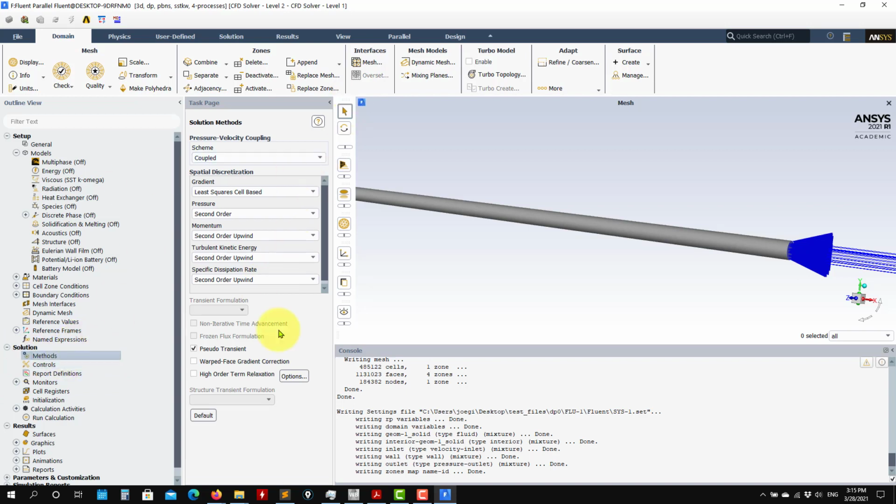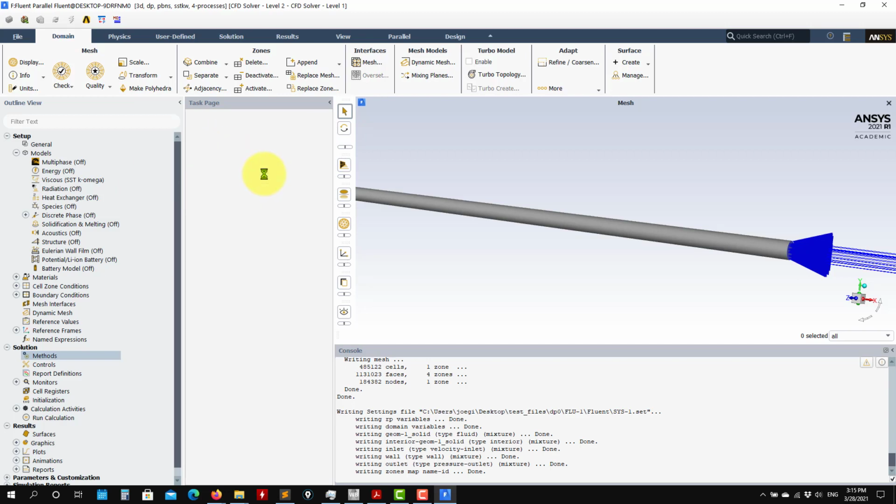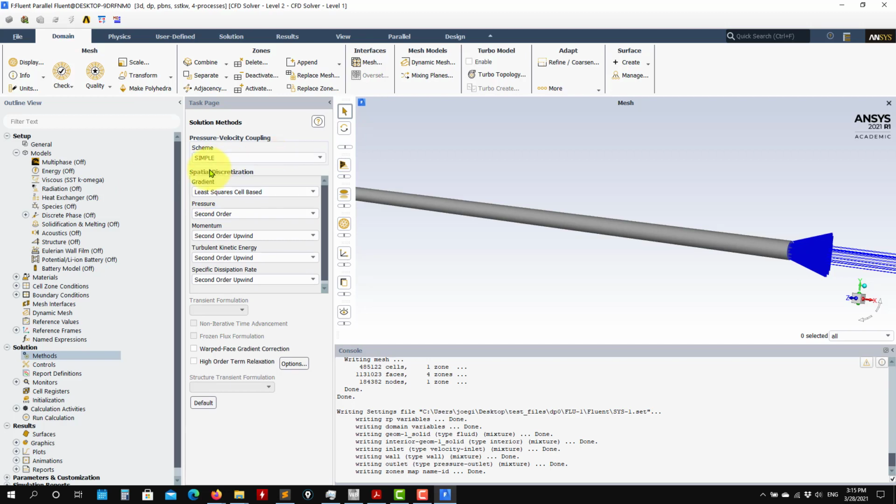So here you have the method. So you have different methods. What is Fluent proposing by default, I think you can take it, it's a good one. But this case in 3D is interesting. Okay, so see here that you have different methods. So you can run, and I invite you to run with the coupled and then run using the simple and check the cost per iteration.